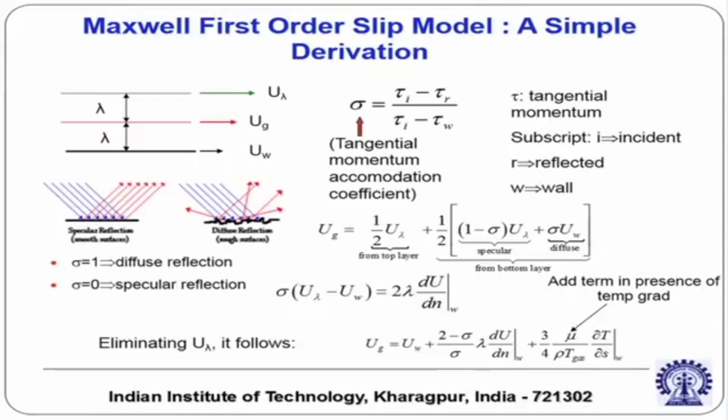If you know what is sigma, by some molecular simulation or from some other source of information, then you can treat the problem like a continuum problem with a modification in the boundary condition, so long as the paradigm of continuum is valid. Otherwise, when continuum hypothesis loses its validity altogether, you cannot use the Navier-Stokes equation with whatever boundary condition.